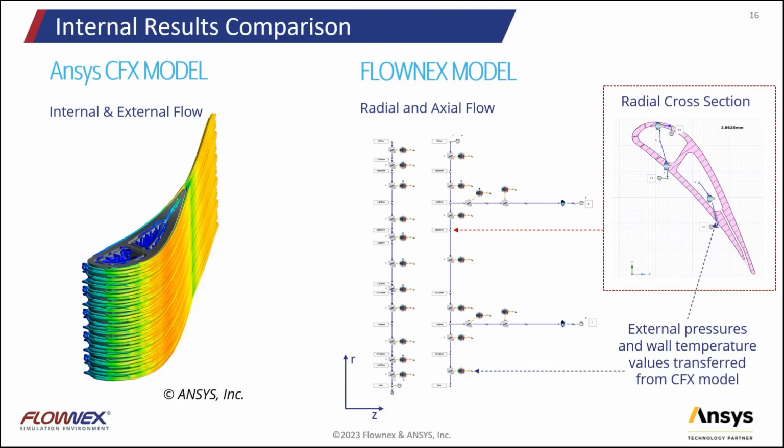At radial locations along those channels, you'll see some labels there indicating the actual radial measurement. There are connections to separate drawing pages or separate representations of the model that describe the flows at different radial cross-sections. You can see a representation of one of those cross-sections on the right-hand side. Here we have one of those holes. We refer to these as view nodes. They allow us to connect between drawing pages, but maintain the same node in the solver. And that representation on the right-hand side connects the flow from that channel, through a nozzle and out through one of the film cooling holes.